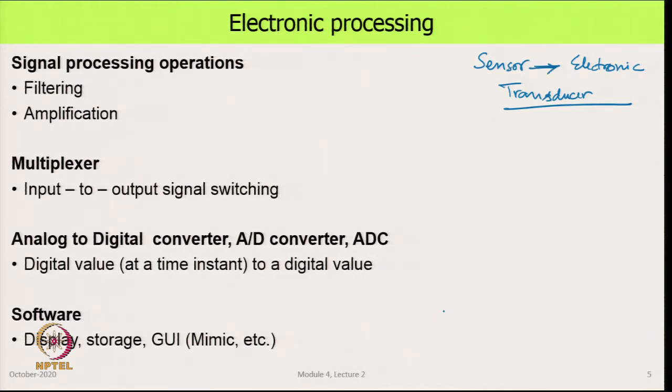Sensors have different types and one is selected so that it can measure some particular property, that means some physical property. This change in physical property causes a change in some other intermediate property inside the sensor, which is then converted into an electronic signal. So, we have a transformation of the physical property to an electrical signal, that is the transducer.